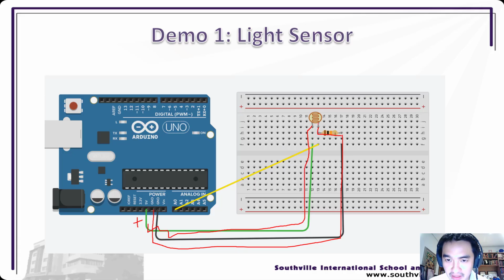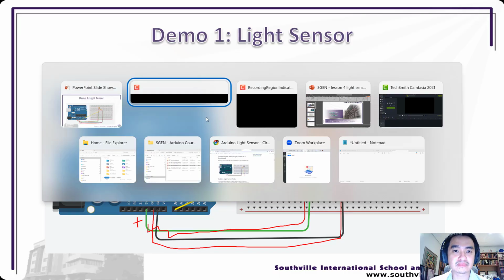And then on the same line as the resistor, we do an analog read here. We're measuring the voltage or the current, and that will allow us to figure out how much light is in this photoresistor. So this is a basic photoresistor program design. So let's get to it and actually build the circuit.